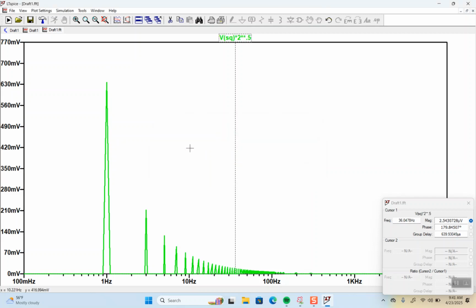And now that's 0.63 volts, right? And there is an analytical equation for that. But if it's not matching, it's because it automatically comes out in RMS. By multiplying it by the square root of 2, because remember, it's all sine waves, right? So it's a way to check your work.